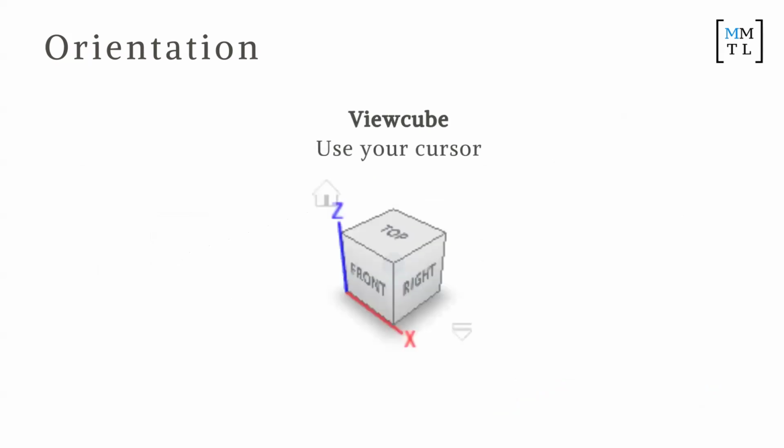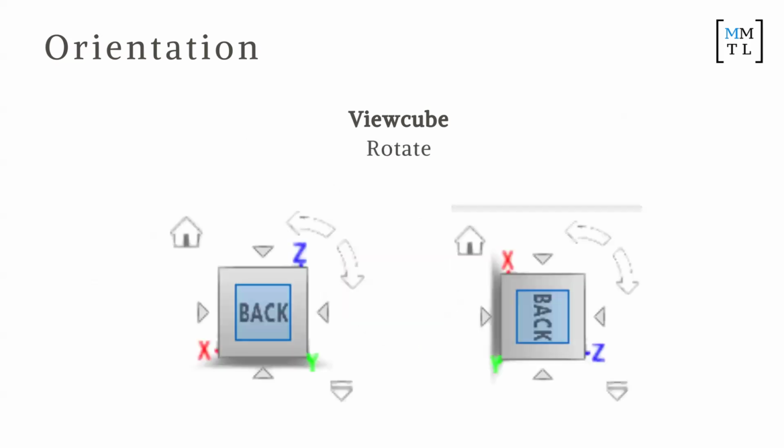On the top right, you're gonna see a view cube. And what that does is you left click it and you can rotate it around, and that's gonna help you move your design around. Top right. You can also left click and drag like that. That's one way to maneuver your viewpoint. And now try to click on each cube surface to reach the different views of your projects. Yeah, simple.